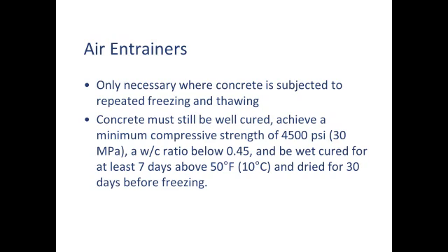Wet cured for at least 7 days, that's to give it enough time to gain strength and for the cement to start consuming some of that mix water, because we don't want a lot of excess water in the mix to freeze and turn into ice. So the lower the water cement ratio and the longer it's cured, the less excess water there is to turn into ice and to cause problems. And then they want that concrete to dry out, basically to get the excess water out of the concrete, in this case 30 days, but I suspect they're talking about slabs on grade, let's say. So I would maybe say a few days at most. It may not even be necessary if you seal the concrete.